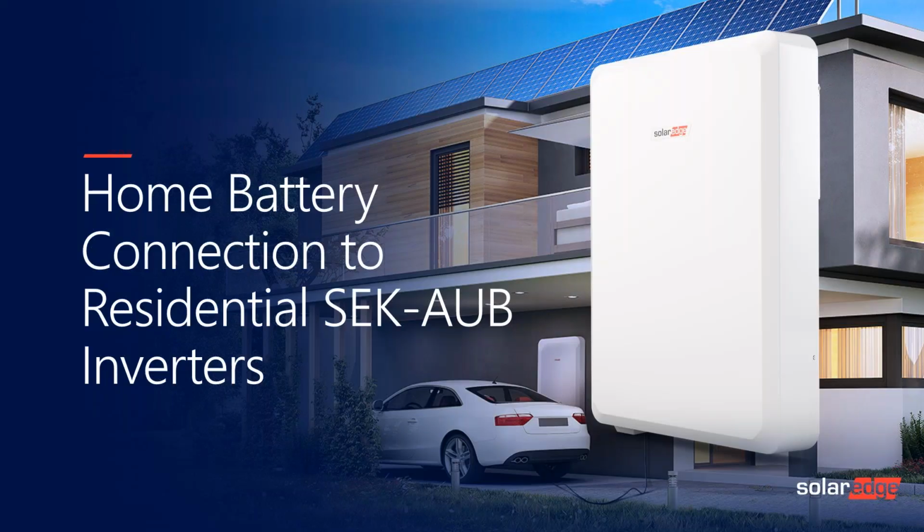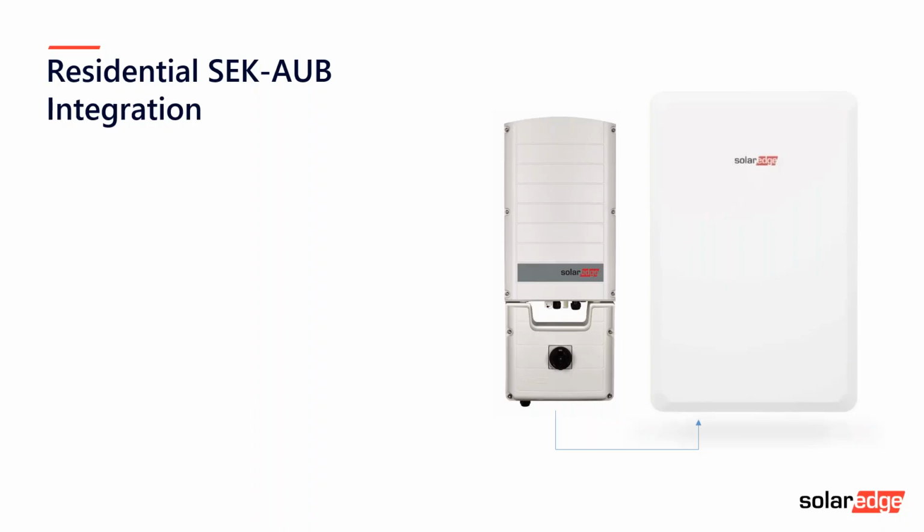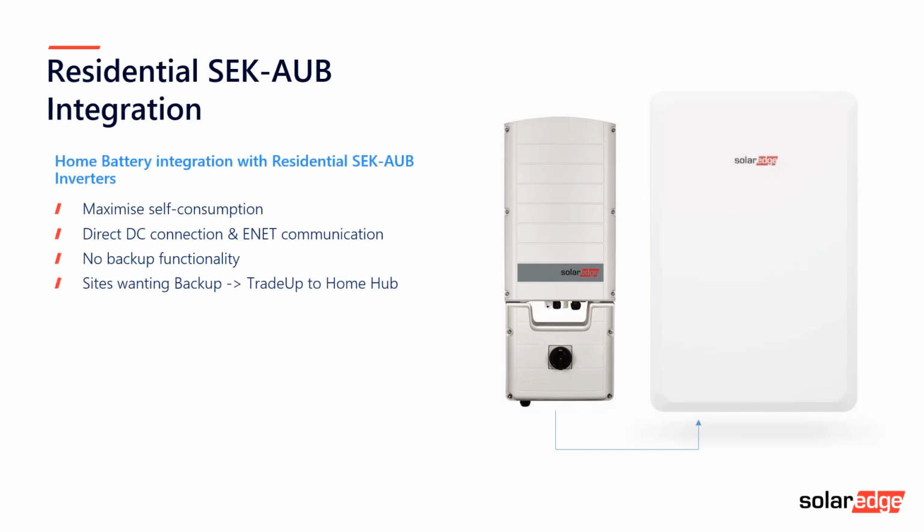Now, some good news, which was long awaited, was finally the integration of the home battery with our residential three-phase inverters. So a couple of key things on this application. There's no backup with this model, and there never was. It's not like the home hub inverter. It lacks a lot of the hardware to deliver backup. But like our Genesis inverter, it will accept DC battery connection for maximized self-consumption applications.